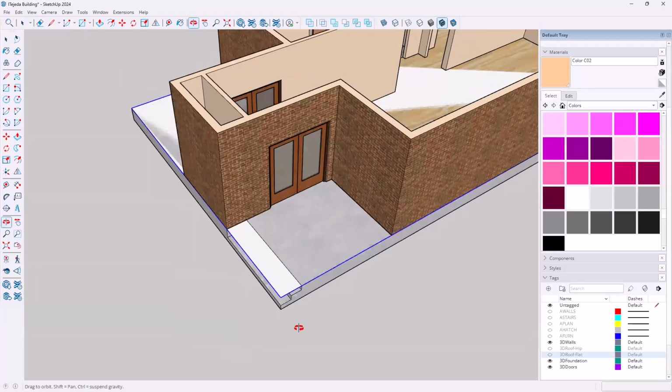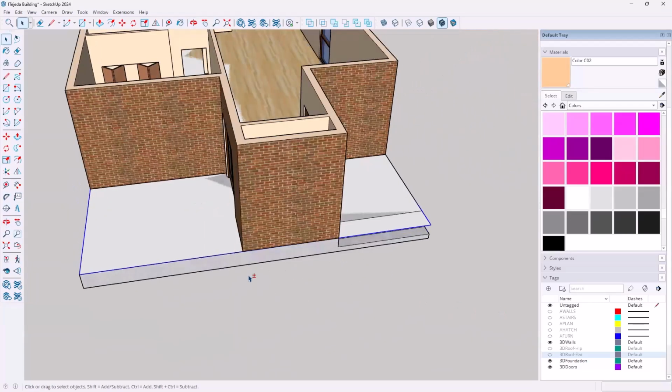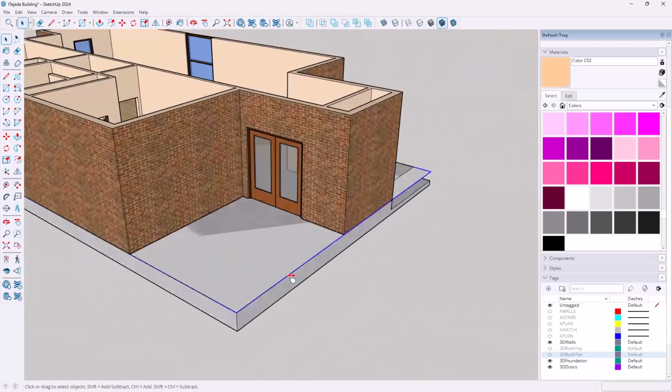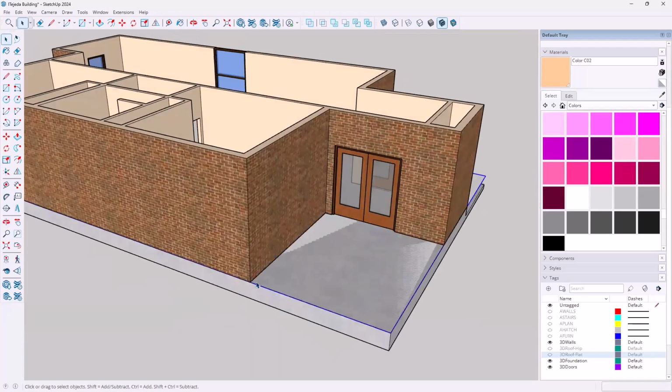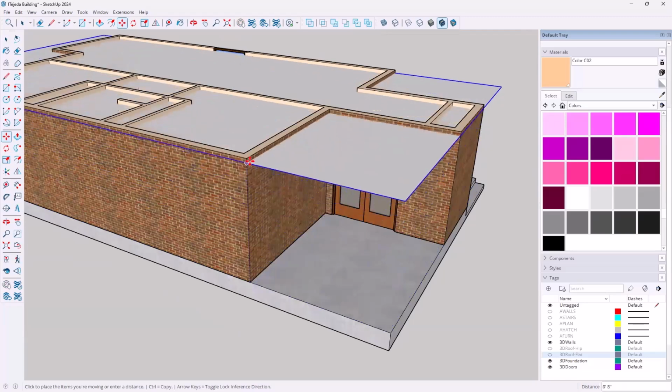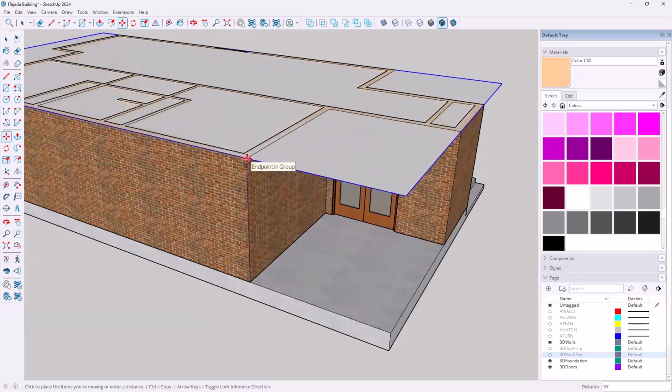And if I want to, now I can move it up. So let me go to this edge right here. And I'm going to type M, and I'll move it from this endpoint up to that endpoint. I did not have to use my up arrow key because I know those 2 points are in alignment. So I'll just give it a click right here.